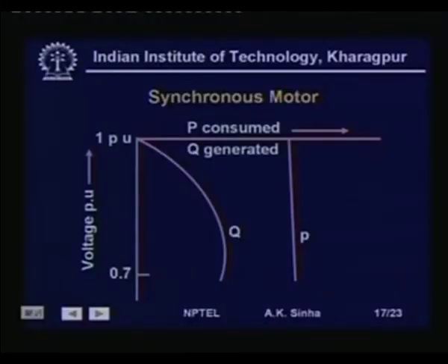Next is synchronous motors. Now, synchronous motors are very rarely used as such. Most of their applications have been either as synchronous condensers, where we want to use these machines for providing reactive power, or in some applications where we need very constant speed, which is not possible with an induction motor, because with change in load, the induction machine power or the torque changes, so speed also changes.